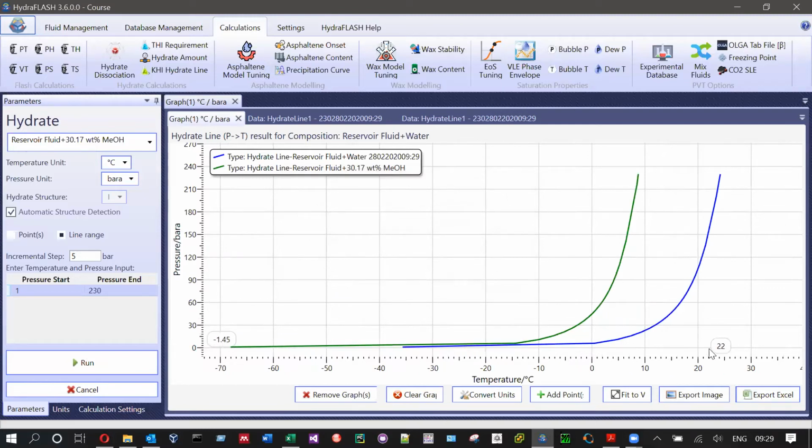Because the blockage was not removed, now we need to check whether hydrate will be stable at very low temperature. For this reason, we need to calculate the composition of the oil after losing the gas, after the pressure dropping to seabed condition.